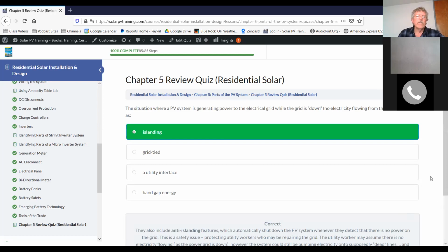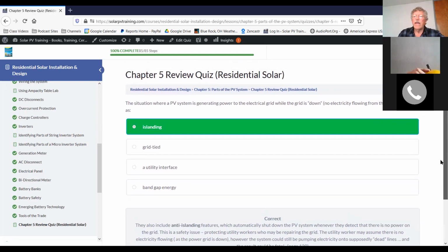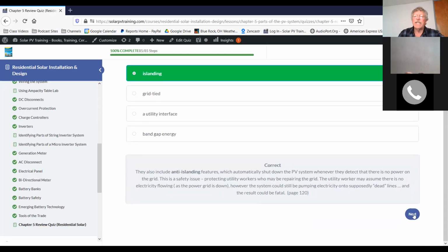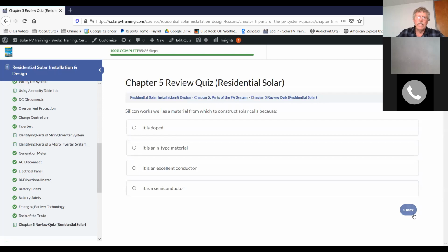So all of our systems are designed to shut down as soon as the grid goes down, except when we've got a bimodal system, which then physically disconnects from the grid and operates as a standalone system. So that's an important concept, and that's built into the inverter rating, the UL 1741. Most of your contracts, most of your interconnection agreements are going to say you've got to have a UL 1741 inverter that assures the utility you will not be broadcasting onto the grid when the grid is down.